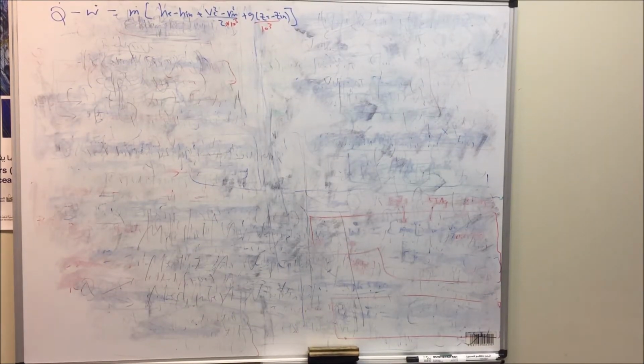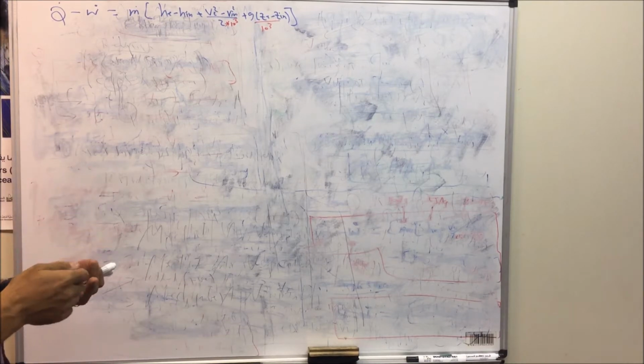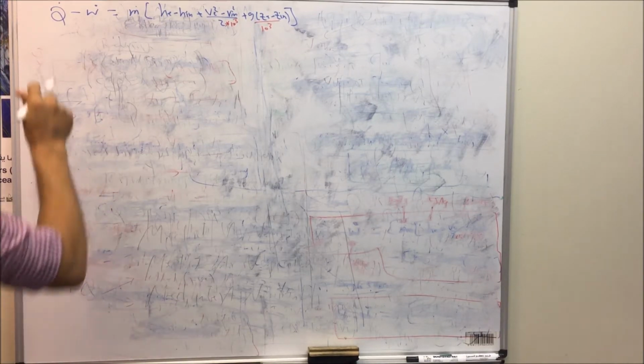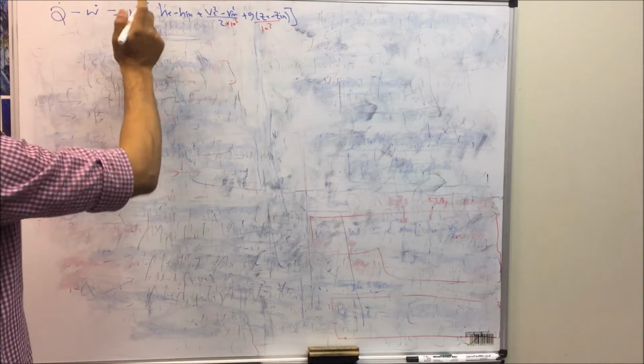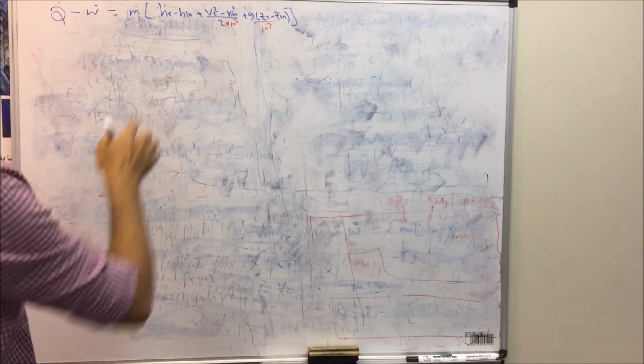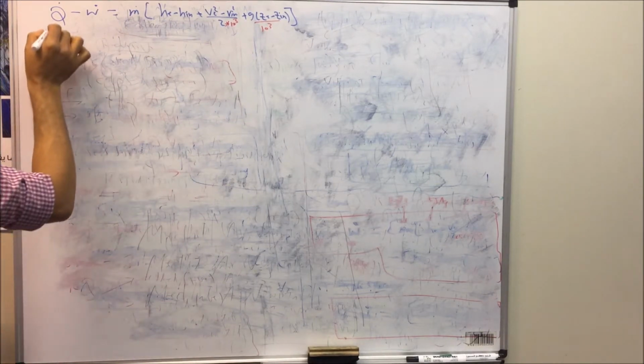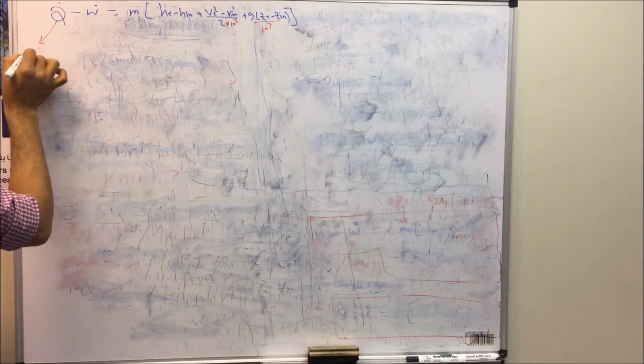And here is the equation again, rewritten for a steady flow open system considering a single stream. So it will be Q dot minus W dot equal to m dot multiplied by the change in enthalpy, h exit minus h inlet, plus the change in kinetic energy plus the change in potential energy. For this term, again, we have to apply the sign convention.